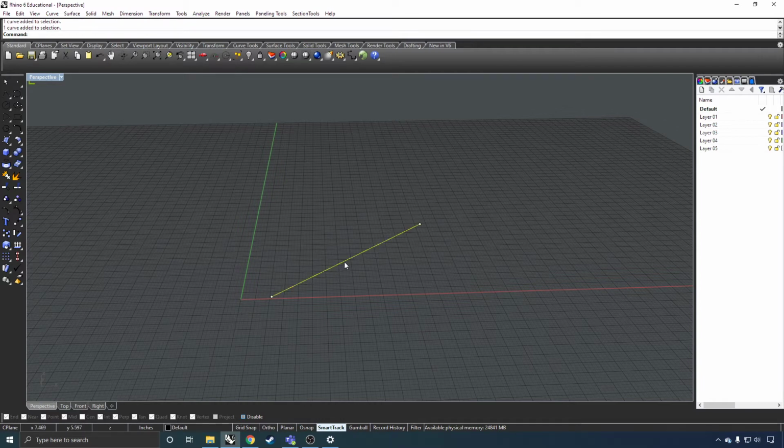You'll notice that I can't move this. I can move this whole thing, but it's kind of floaty. It's very imprecise. Generally, if you're trying to move things very precisely within Rhino, you're going to want to use a command for that, similar in Revit, where you would just type MV for the shortcut. Here, you're just going to type in move and then hit enter.